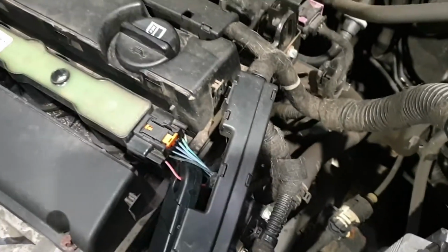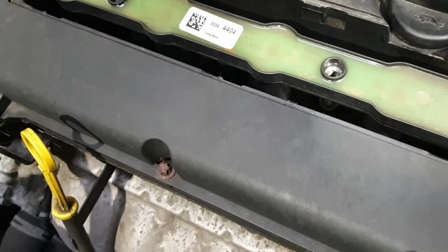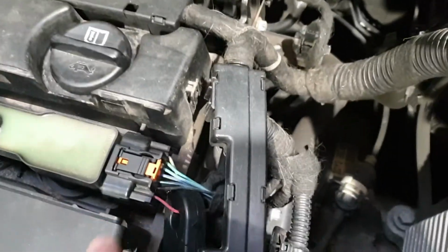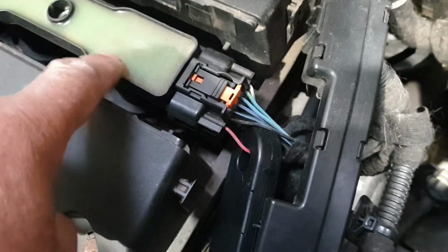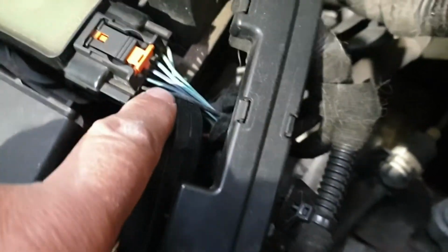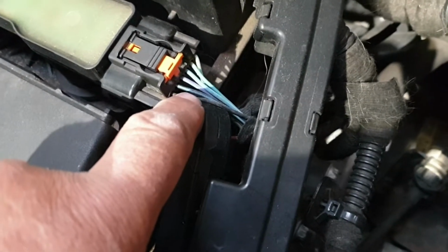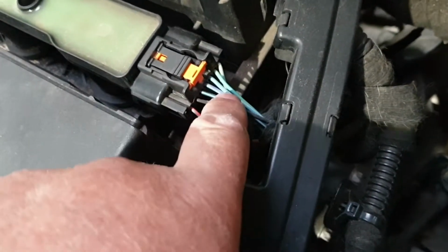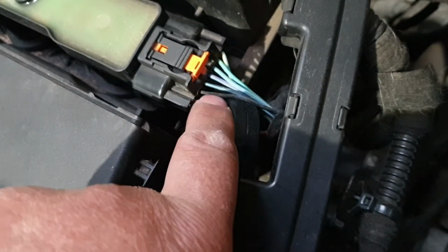So now I'm going to check the ignition coil pack current flow to the primary circuit of that. So this is the feed for all 4-cylinder ignition coils, and the second one is the ground circuit, and also this one is ground as well, the third one.